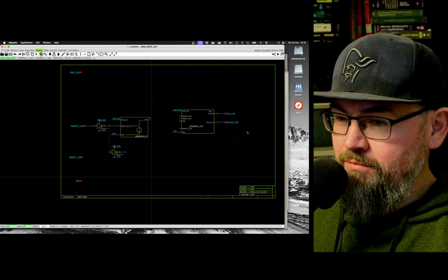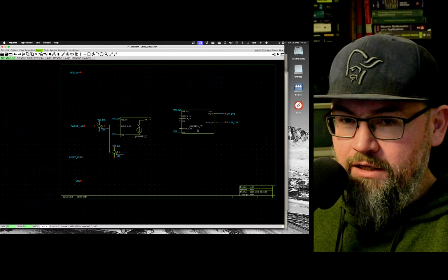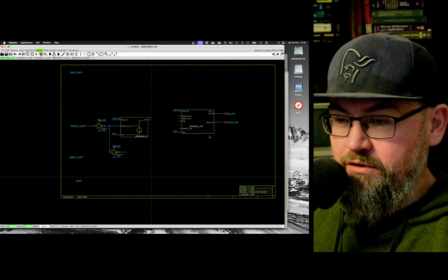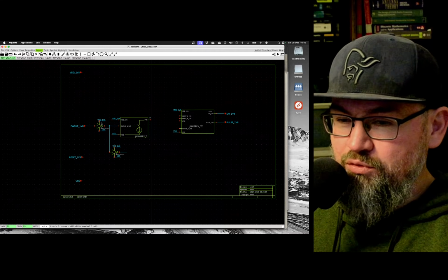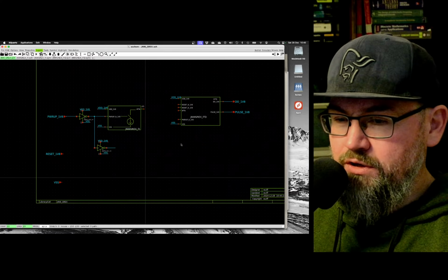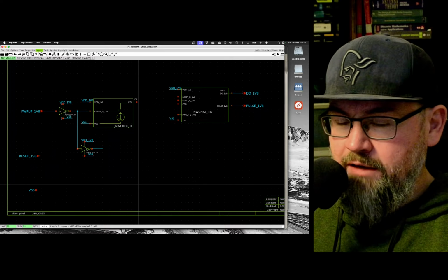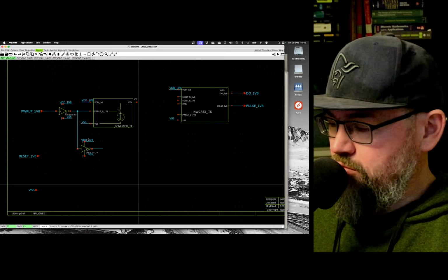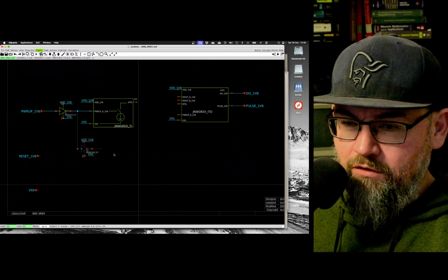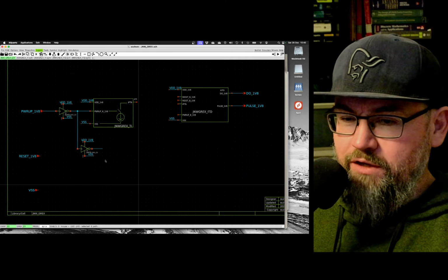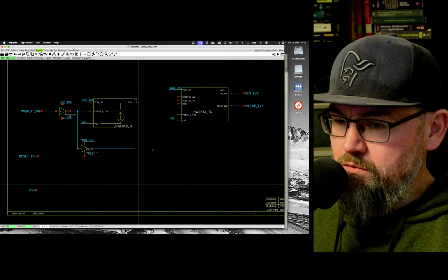It can come from a driver that is very far away and maybe on a slightly different supply. So you kind of want something to regenerate the voltage before you put it into at least transistors. So I like to have at least an inverter or something like that to regenerate the signal levels. So that one's the buffered.